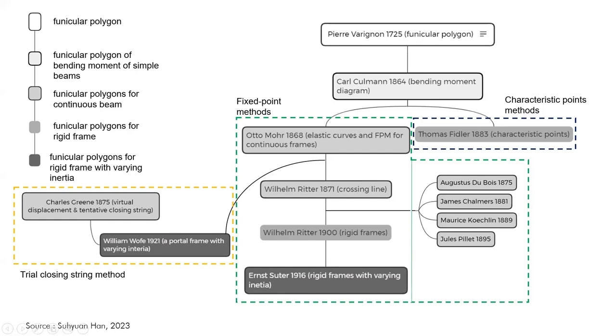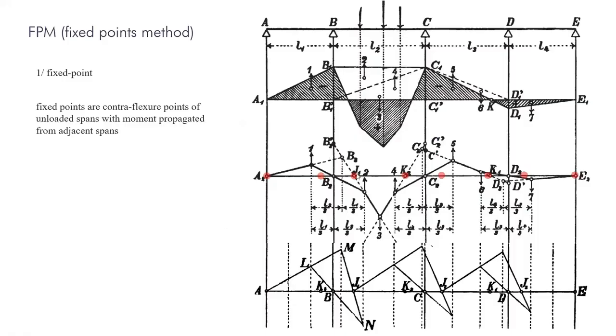So what's the principle? We have to define a fixed point along the structure through which we have to make a line passing, for constructing graphically the balance of force between the several spans that will be met for this system. It can be done graphically as here, and this can be done also with an algebraic process.